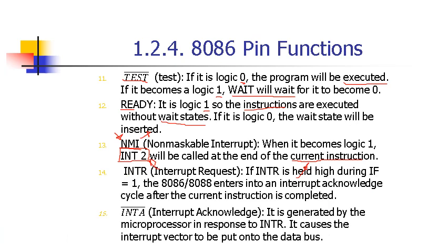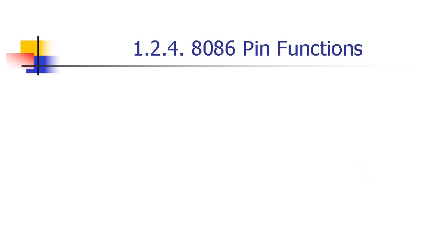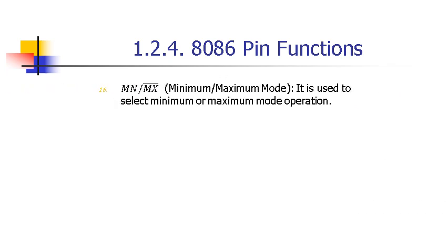Okay, you're handling a hardware interrupt now, so your interrupt should go high. Your interrupt flag bit is also high, and the interrupt is being served, and this is indicated by the interrupt acknowledge when it's low. If this pin is high, it means your processor is in its minimum mode.